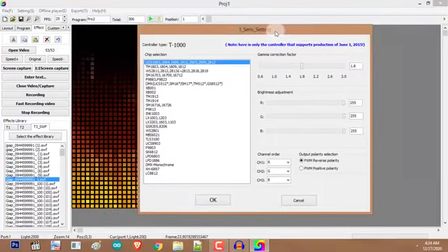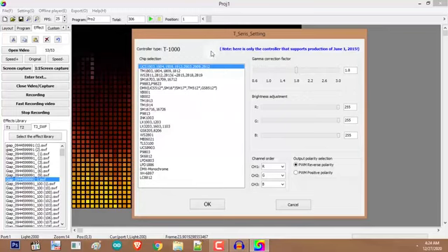Alright, once you select that, you will get these T-series settings. Select the pixel LED number that you are controlling. In my case, WS2811. These are the drive chip numbers of your pixel LED strip or string. You can select the gamma factor if you do want to change the gamma effect of your pixel LEDs. It will increase the whiteness of your pixel LED strip or string. Use this slider to set the gamma correction factor. I will leave the default value.